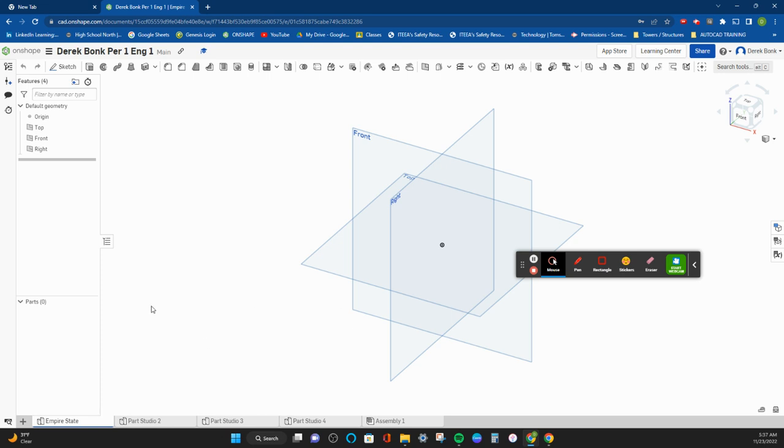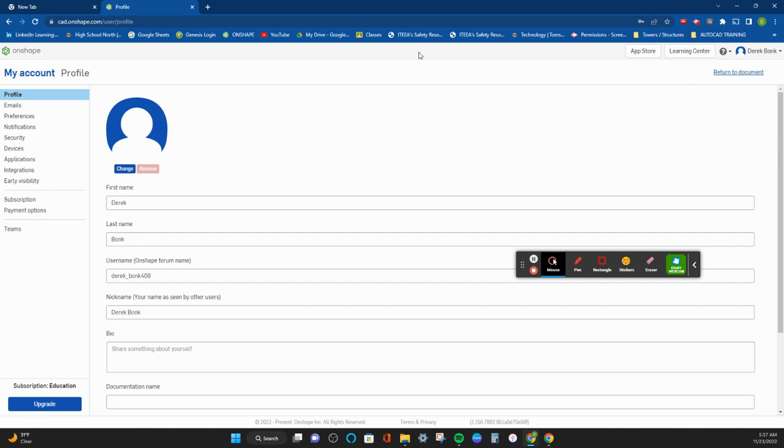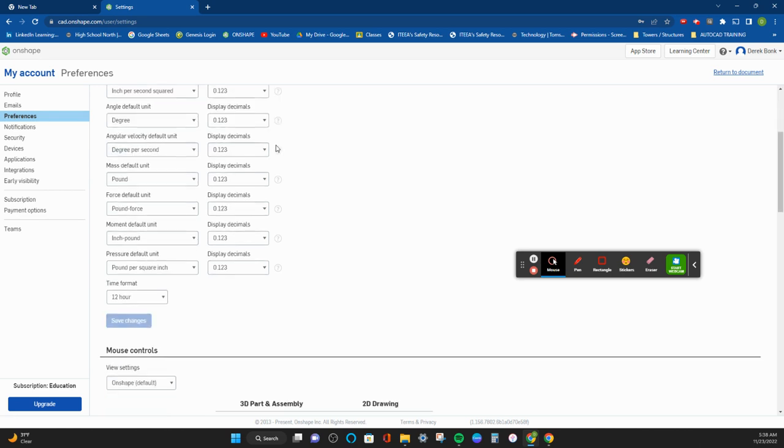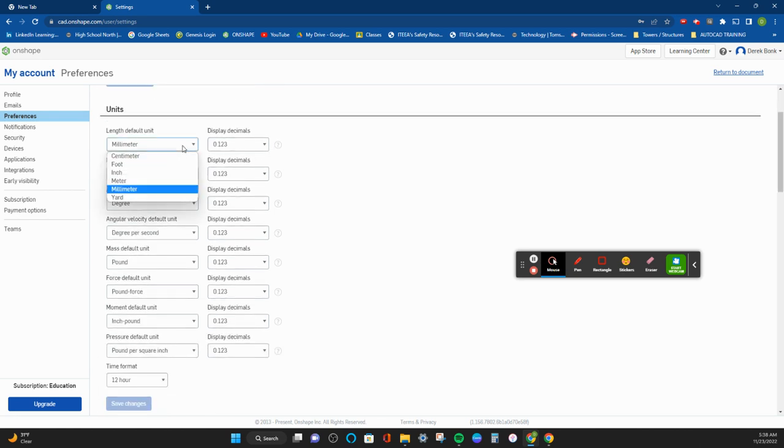Anyway, the other thing that you need to have certain is that your account settings, if you go into where your name is up here, your account settings have to be set up the right way. For your preferences, you have your unit standards. It defaults, this is a company based out of Ohio, actually, so it defaults to American Standard, but all machines that we use are going to prefer you seeing metric, and millimeters is the easiest way to design in software like this when you're dealing with 3D print work like what we're going to design.